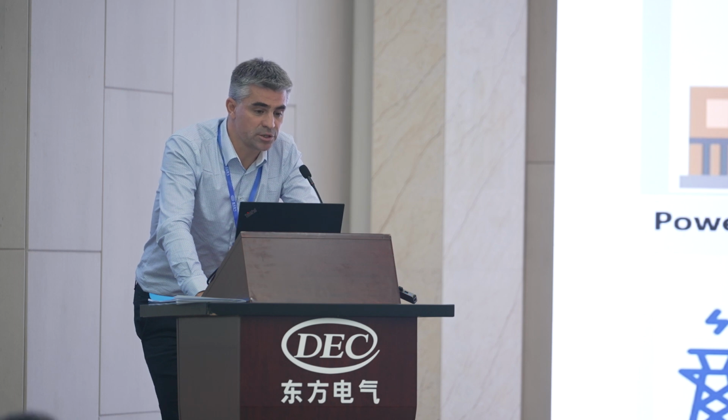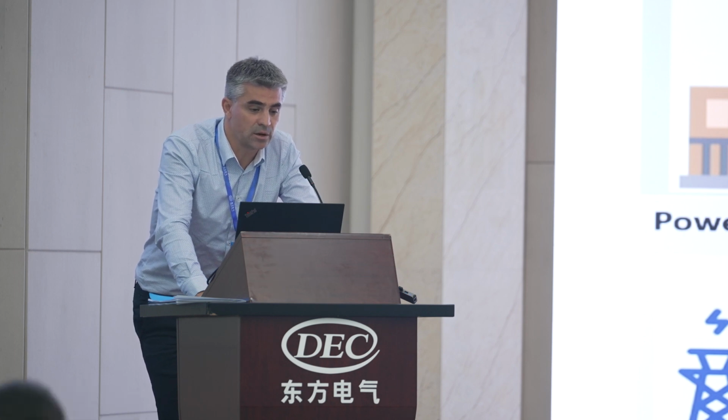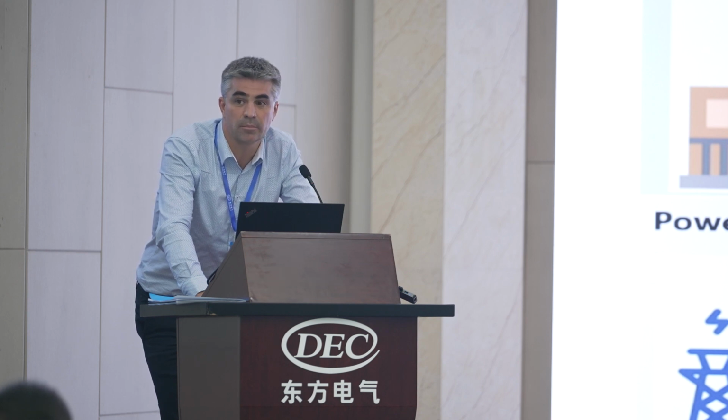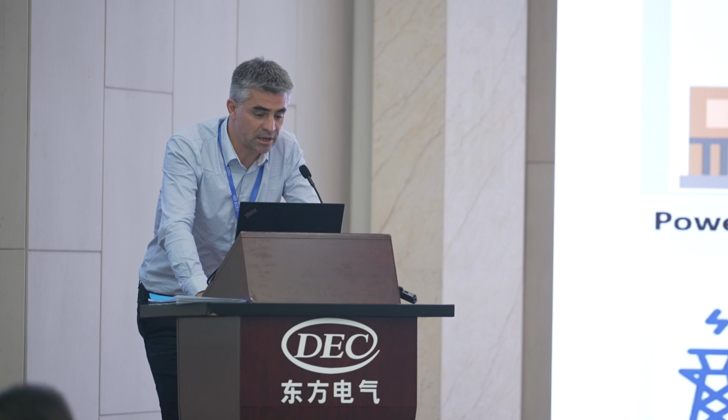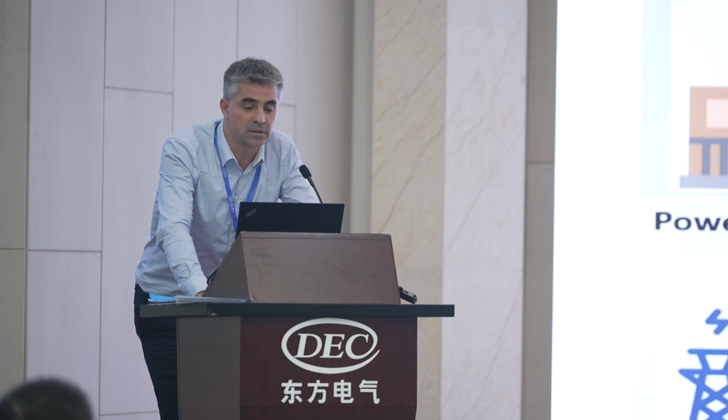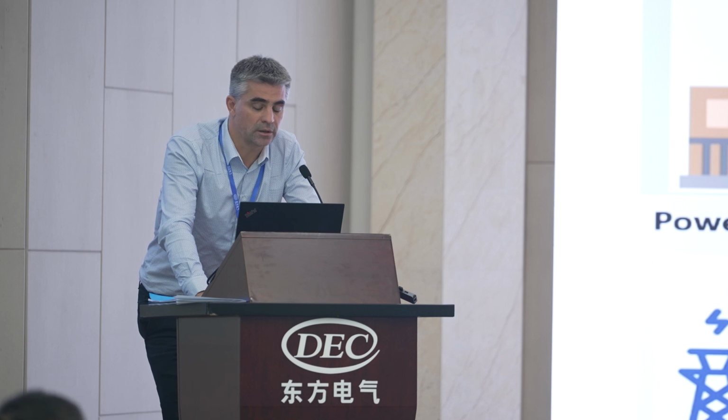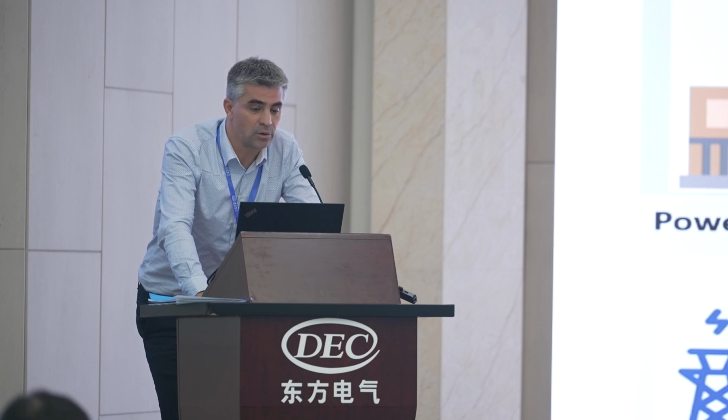For this process simulation, we consider two design cases. A refinery case with a generation of 100 ton per hour of steam and 50 megawatt of electricity. And for our second application case, it's only a production of 200 megawatt of electricity. So this second work consists in having a complete process simulation of the CFC, including the reaction section, the flue gas treatment, the heat recovery and production of steam and electricity, and finally the CO2 capture and compression.